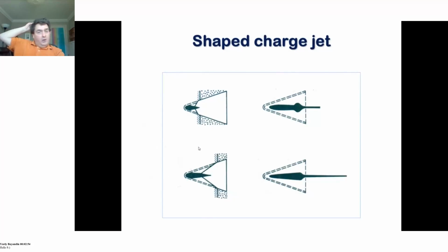So you've got a hollow line, a line cavity inside the explosive, and the detonation wave goes down. It collapses the material and forces the jet out in a line, and it's hydrodynamic, so the pressures there are so large that the metal moves very much like a liquid, and it's also been compressed quite a lot as well, so it's rather like a hot liquid jet of metal.